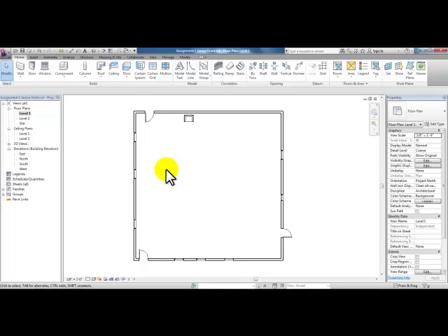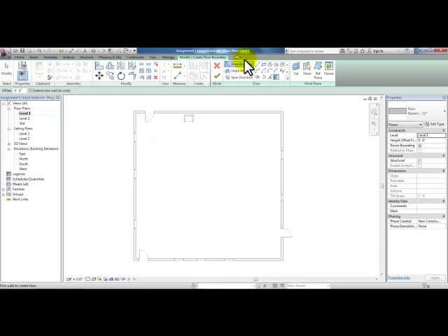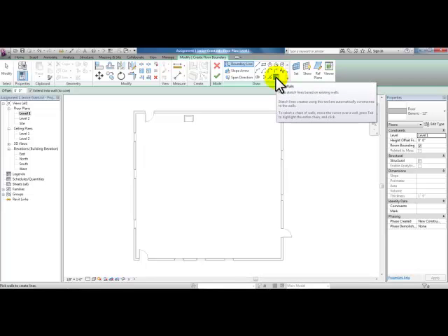Now let's take a look at establishing a floor. In the level 1 view, we can go to Floor in the Home tab and pick Floor here. In the ribbon, there's an area called Draw, and by default this icon here is called Pick Walls. You're sketching the outline of the floor, and one way to sketch the outline of the floor is to pick the walls.